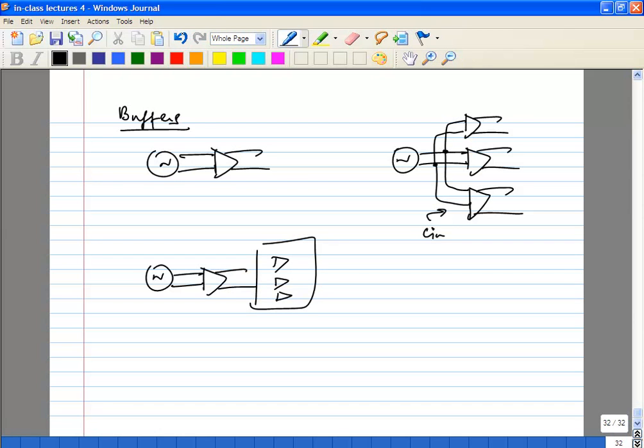Okay, you can have a 2-stage buffering. So this will definitely help with that. So your C in here is reduced. Obviously what you're trading off is power consumption. The minute you put in a second stage, you'll have to worry about more power consumption.